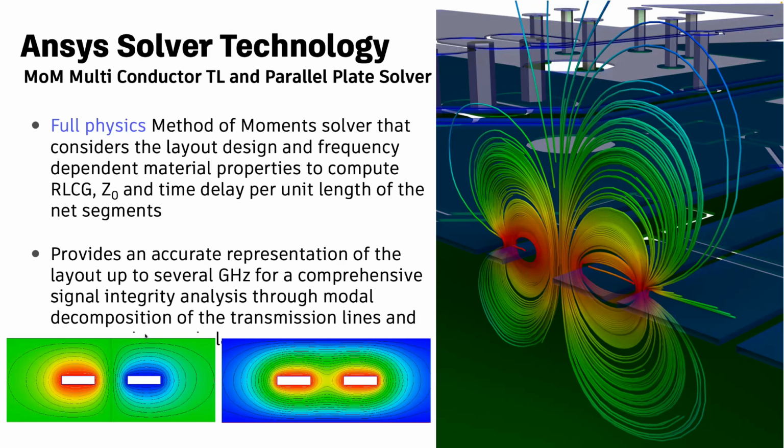One of the most important outputs that we have from this solver is the impedance of the traces, like Matt was saying, right? It's very important to control the impedance, and not only on RF lines, let's say where you're feeding an antenna, because it's not only just real impedance, like let's say 50 ohms, but we also have sometimes to match imaginary impedance, which is one of the outputs of this technology.